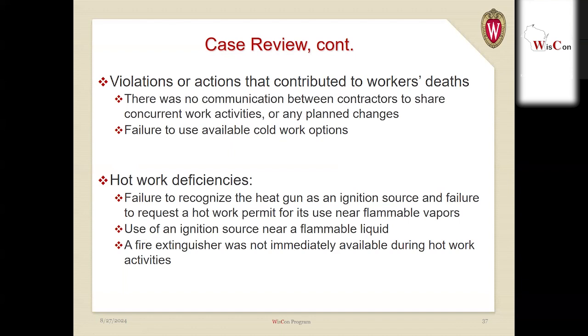When it comes to hot work deficiencies, there was a failure to recognize the heat gun as an ignition source and a failure to request a hot work permit for its use near the flammable vapors of that resin, and again, the use of that hot heat gun near a flammable liquid. Additionally, a fire extinguisher was not immediately available during the hot work. At one point, if you read this case study, they tried to use the top of the resin bucket, which just ignited and melted, causing the fire to spread.